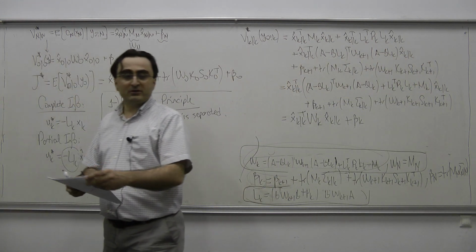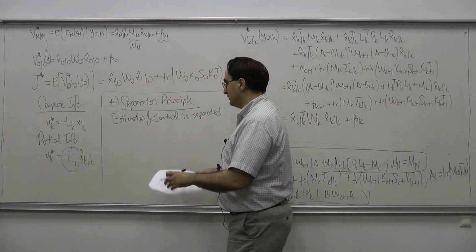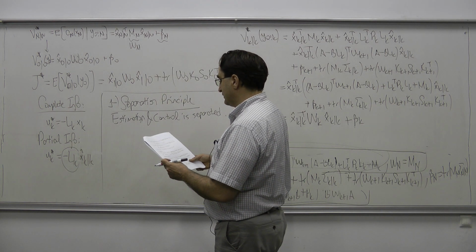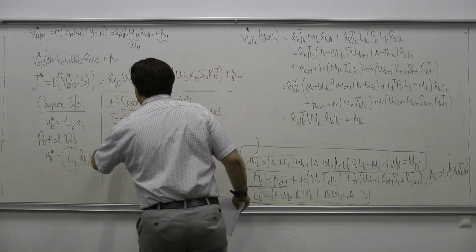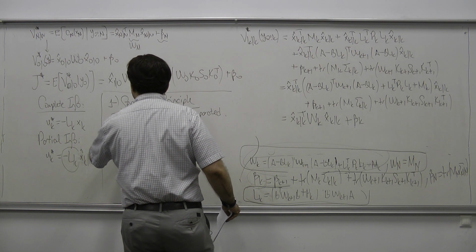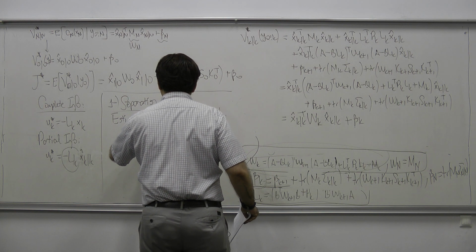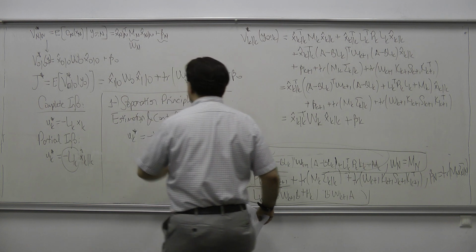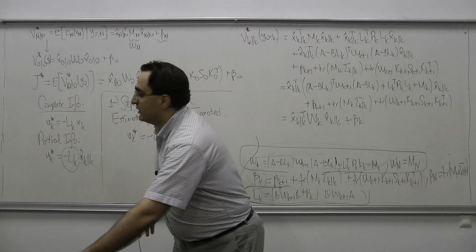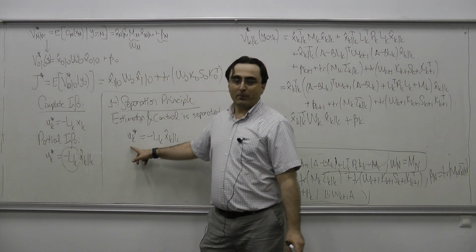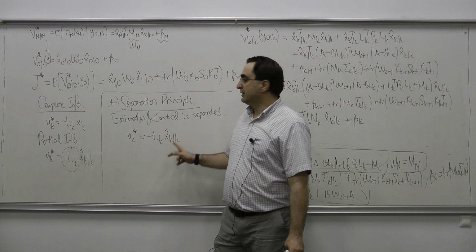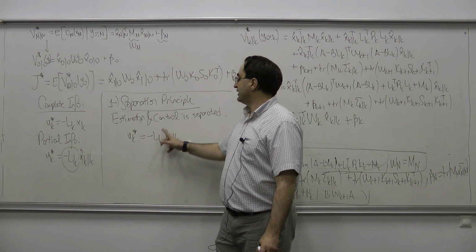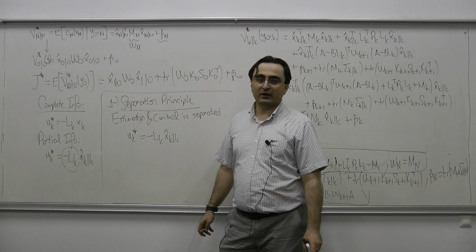And this is the optimal feedback case in the linear Gaussian case. So for this type of feedback policy, UK star equals minus LK x at k given k, we see that the dependence of this optimal input on y0 to k is only through the estimate x at k given k.